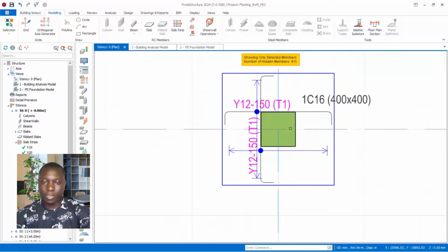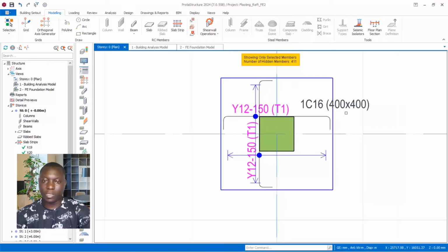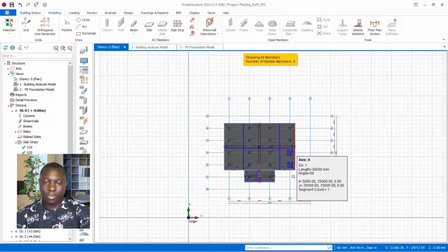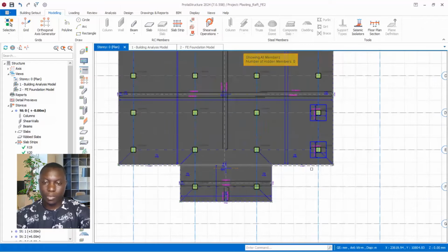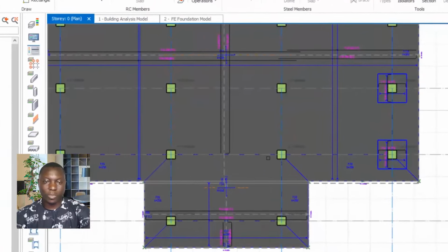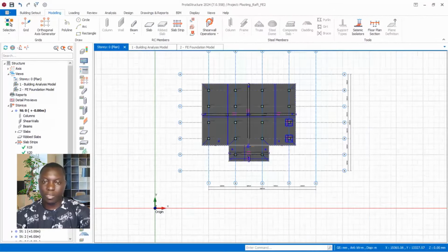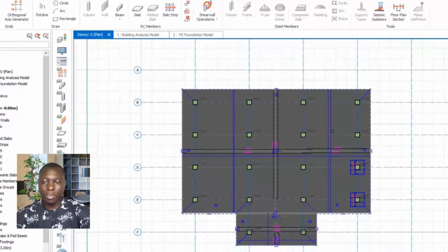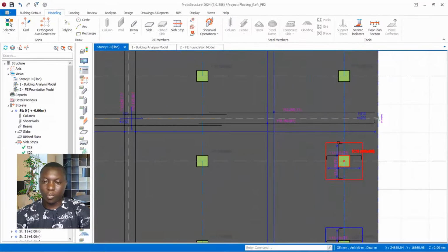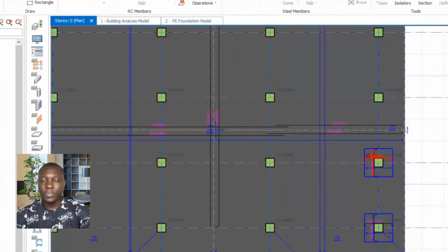You see the reinforcement here being created successfully, just like this. So I can select this, right click, and show all. So this is what I have. So in our detailed drawings, we will use this information for all of these other columns that you have not yet placed, because we'll be using the same column footings or drops, dimensions, and depth successfully.